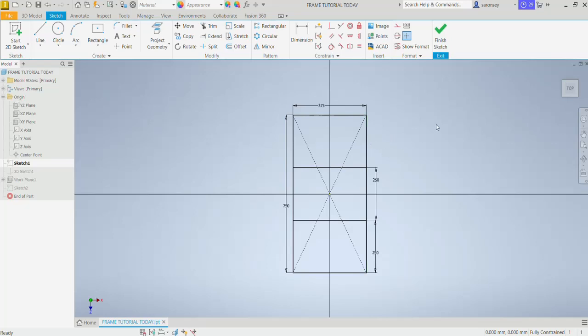I mentioned earlier we will be using some constructional lines. So let's click our line command and make sure it's construction by choosing the construction command up here. We'll select it and draw a constructional line. So at this point, draw one constructional line, make the length 150, enter, right click, OK. Choose the line command again, make sure the line is constructional line. When this is highlighted, draw a second constructional line, also 150, enter.